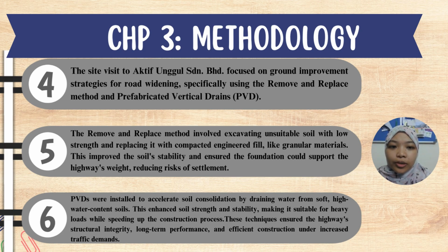Assalamualaikum warahmatullahi wabarakatuh. My name is Nur Aifatah binti Mauburhan and I will present the methodology. The site visit to Akif Unggul Sdn Bhd focused on ground improvement strategies for road widening, specifically using the remove and replace method and PVD. The remove and replace method involves excavating unsuitable soil with low strength and replacing it with compacted engineered fill like granular material. This improves soil stability, ensures the foundation can support the highway weight, and reduces the risk of settlement.